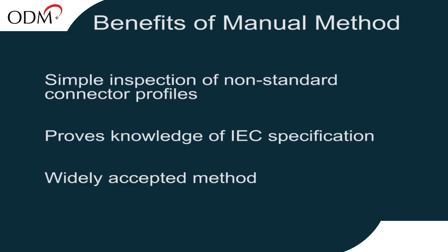There are some situations where manual analysis of fiber end faces is preferred over automated analysis. These include situations where a connector has been improperly polished but is still functional, or when a customer requires proof of fiber grading expertise from a test technician. In fact, the manual grading method is the widely preferred method, except in cases where the user lacks the proper knowledge to employ it effectively.